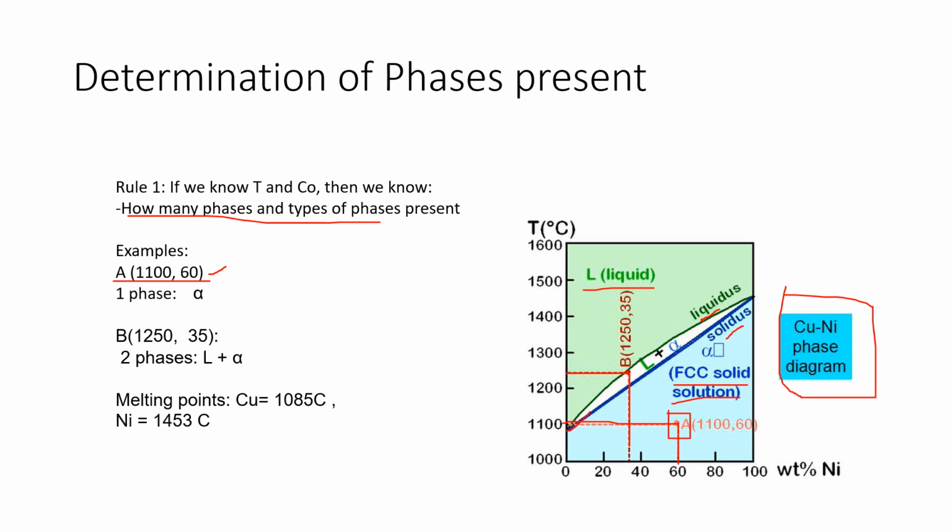If we look at the solidus line, above this line liquefaction begins, and if we look at the liquidus line, above this line the mixture is completely liquid. Below this line, solidification begins. Within the liquidus and solidus region, we can see a mixture of liquid and solid solution.